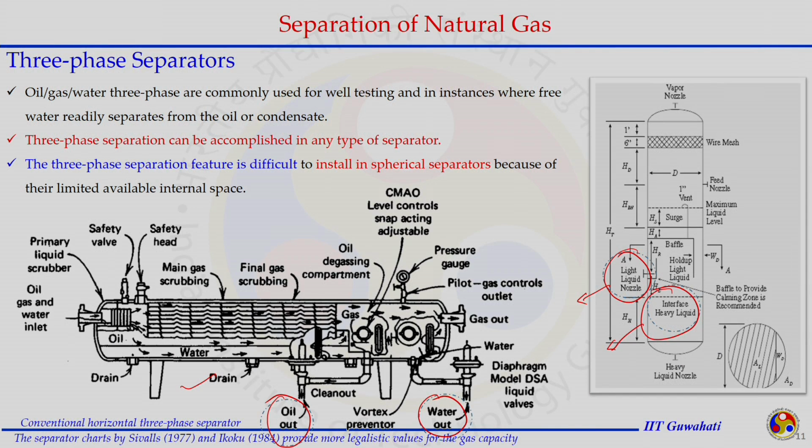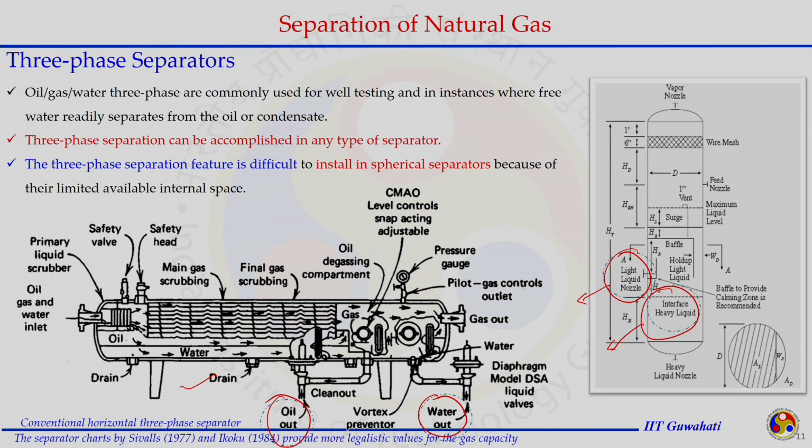The feature of the three-phase separator is that it is very difficult to install in a spherical mode because of the limited available internal space. So, if we are talking about a three-phase separator in a spherical geometry, we have the difficulty. Otherwise, oil, gas and water separators are commonly available for two-phase as well as three-phase.